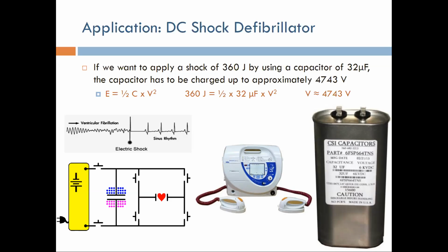There are other applications, by the way, where you use capacitors to store thousands of volts, and in each of them, it's exactly the same. Regardless, some people think DC is not dangerous. Actually, DC can be very dangerous when the voltage is high enough, okay? Because it can pass current that is dangerous enough to cause harm to the human heart, or the human body. It can sometimes cause burns in the human body. So just keep that application and that safety tip in mind, okay?